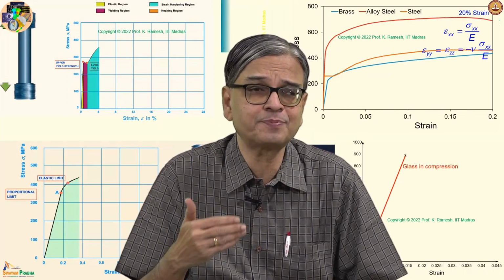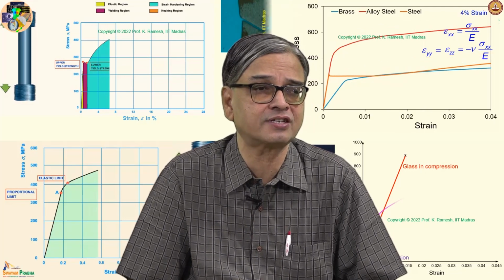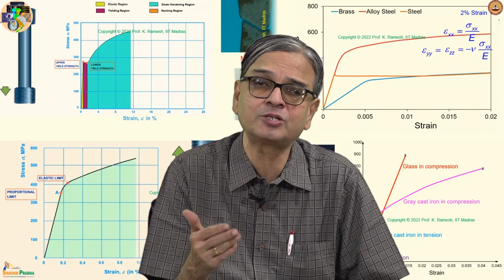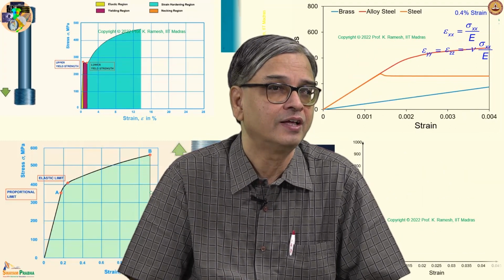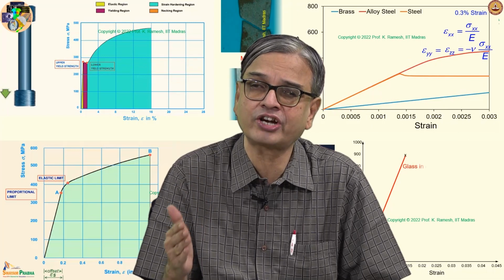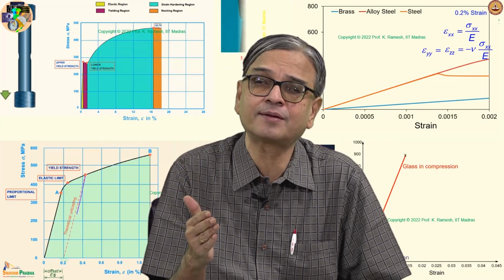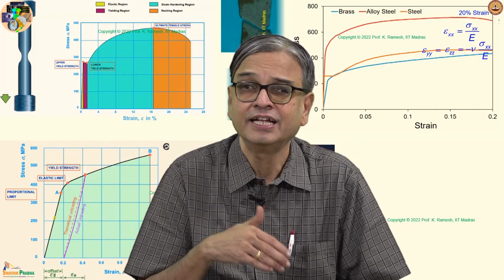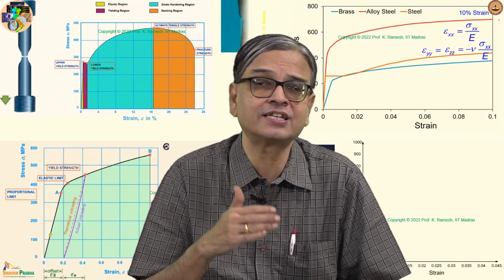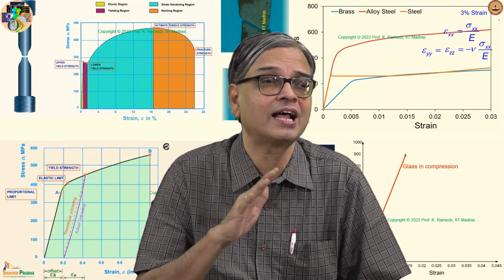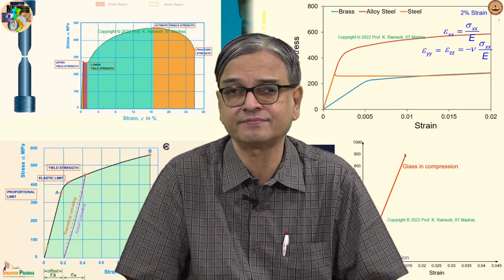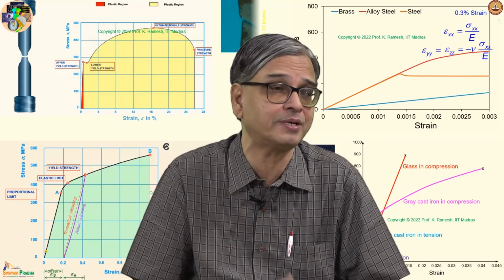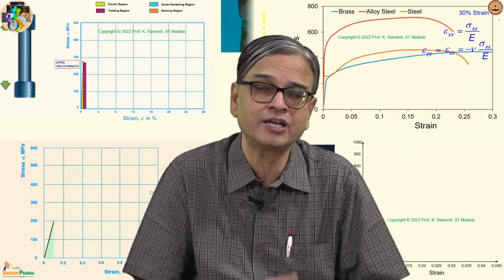And another aspect is, we have studied state of stress at a point. You have determined the principal stresses. You have also determined the principal stress orientation. When we went to state of strain at a point, we also discussed the directions of maximum axial strain. These principal directions and principal planes are identical for an isotropic material. That is not the case when you go to an orthotropic material or an anisotropic material. It can in principle be different depending on which way you load the system.